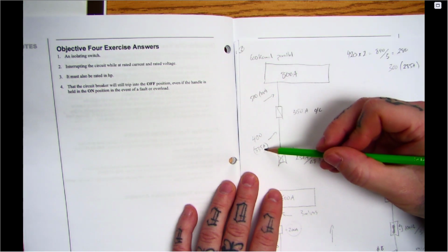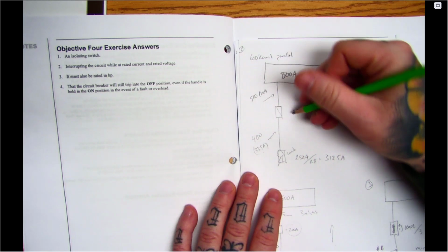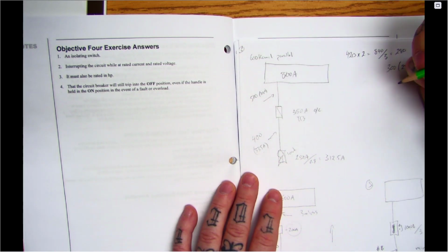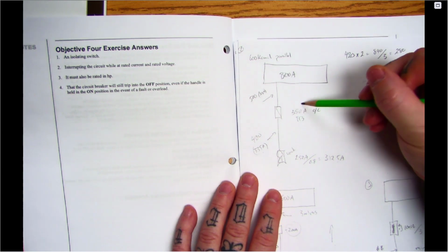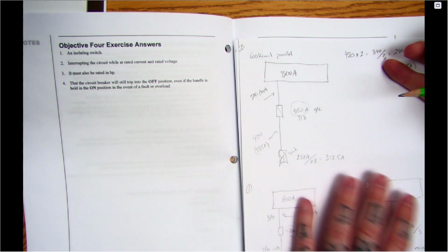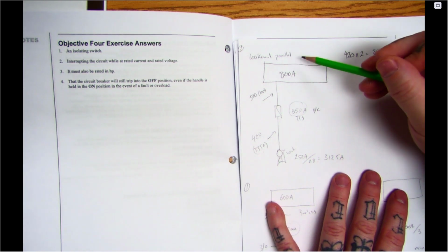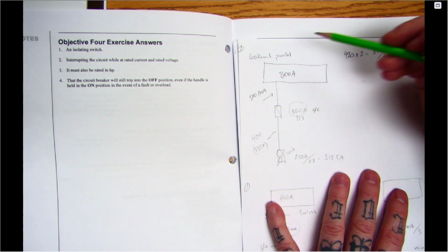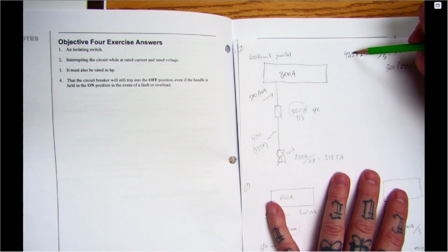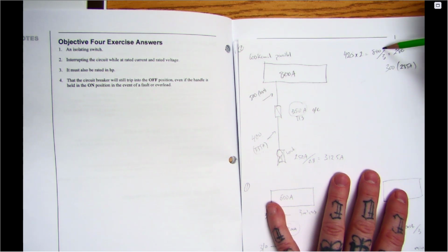So when we go to table 13, the 335 is going to put us into 350, from table 13. Now, this is a scenario again where we're either using this, or we're going to use a third of the feeders, whichever's largest. Because I have parallel runs, I find out what the 600s are good for. They're good for 420 amps from table 2, 75 degrees. Times that by 2, get 840. Now I'm going to use the third of my feeder conductor rule, so I get 280 amps.